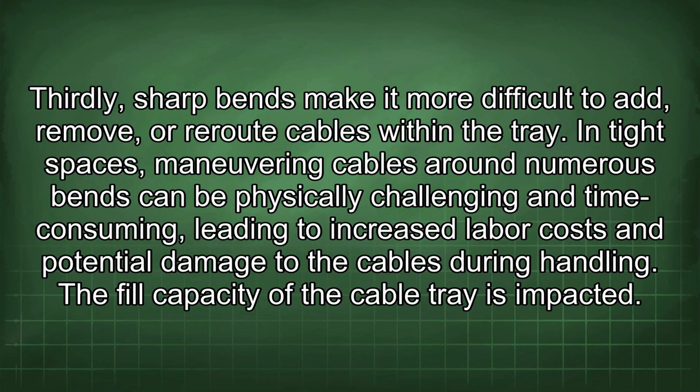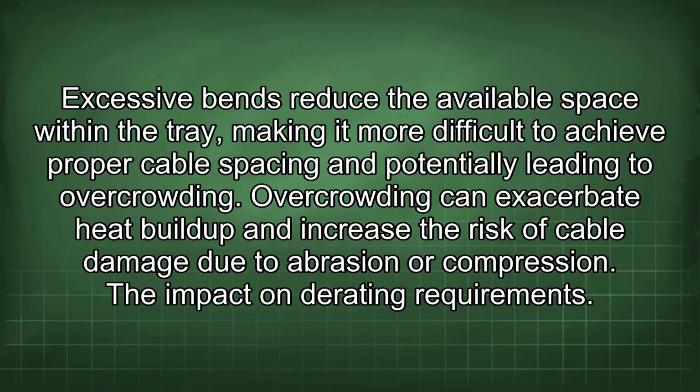The fill capacity of the cable tray is impacted. Excessive bends reduce the available space within the tray, making it more difficult to achieve proper cable spacing and potentially leading to overcrowding. Overcrowding can exacerbate heat buildup and increase the risk of cable damage due to abrasion or compression.